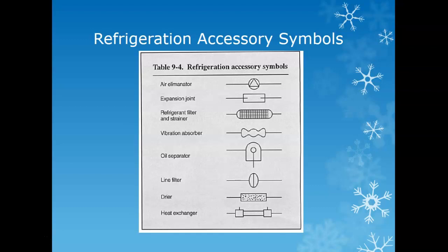If you have any kind of an enclosed system, anytime you have a type of enclosed system, you should always, always, always have a filter of some sort built in. Why? Because it takes nothing for any type of fluid to pick up something that it shouldn't.